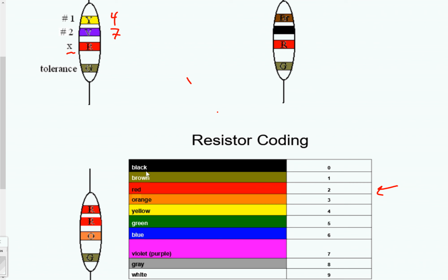That's it. If you had a brown band, you would multiply by 10, 1, 0. So if this was a brown banded third resistor, we'd multiply by 10. This would be 470. Well, this is a red third band, which means we multiply by 100. You should be able to figure this out. Multiply by 1,000, you just keep adding a 0. So brown means multiply by 10. Red means by 100. So all you have to do is this. 47 times 100 means this is a 4700 ohm resistor.